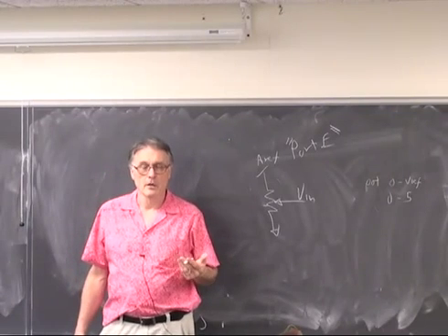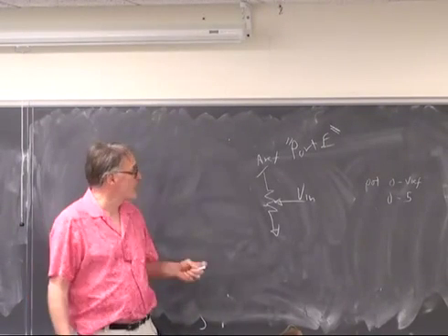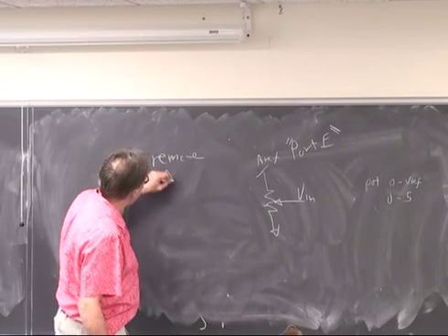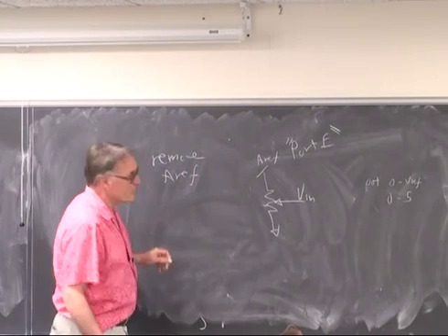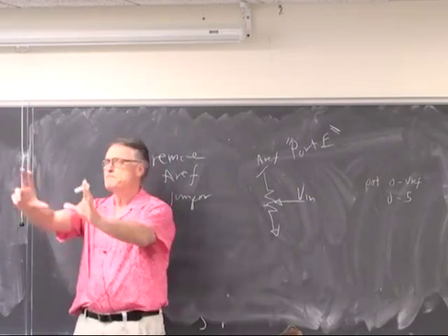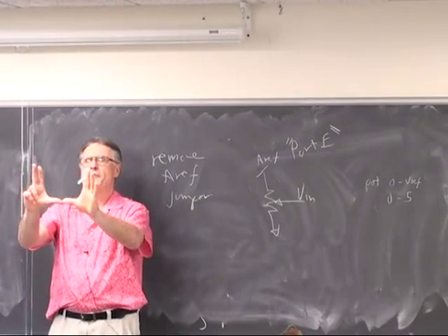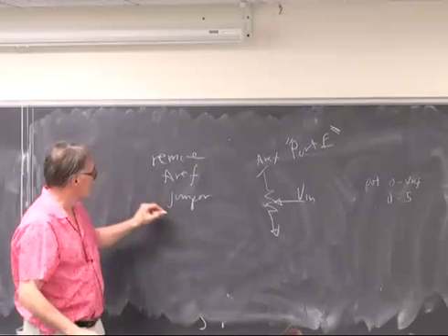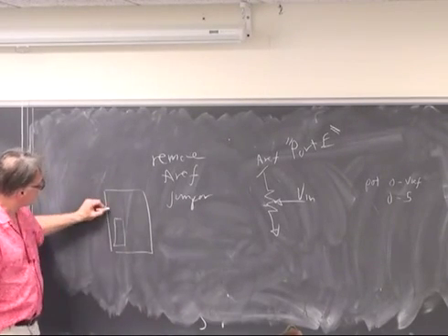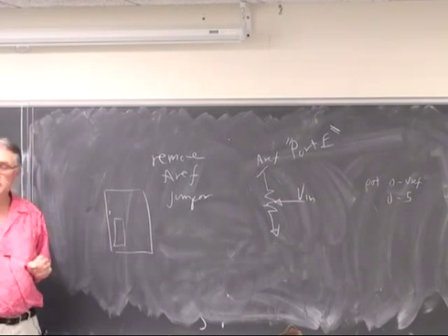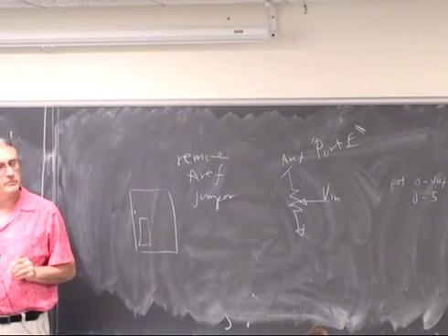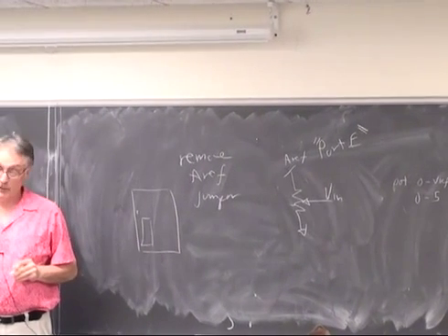Jumper. Oh yes, well yeah, I think I said that once, but I'll say it again. You must remove AREF. You have to unmount the AREF jumper, which is, if you orient the STK500 with the microcontroller at the bottom left corner, then the first jumper here is what? You have not memorized them yet? You better.